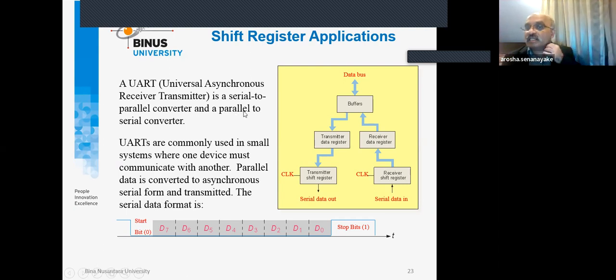In the end, before being transmitted onto the data bus, there is a buffer. Why do we require a buffer? Of course, you know very well that the CPU is faster than any of the externally connected circuits. The CPU might have a much higher frequency than these circuits.